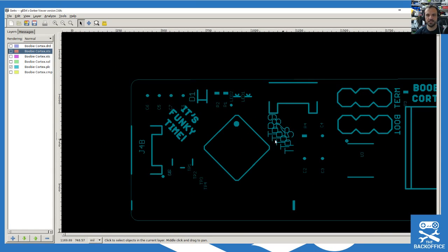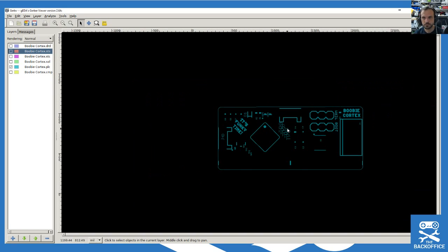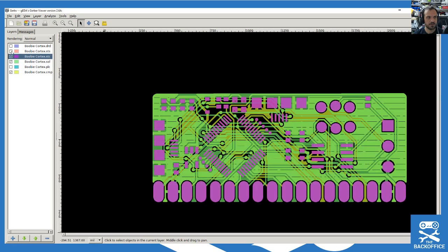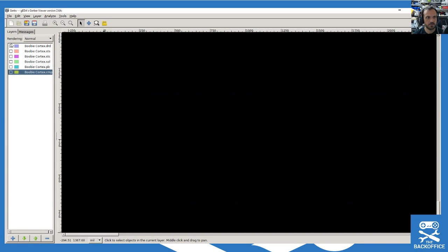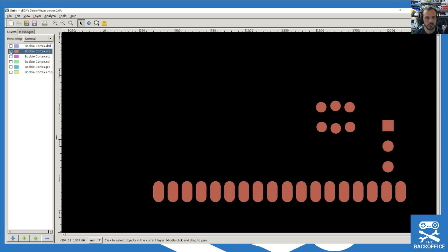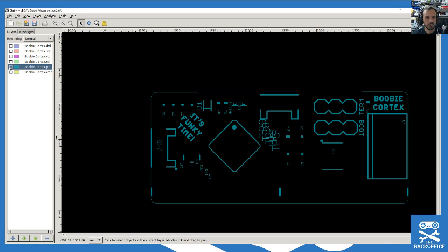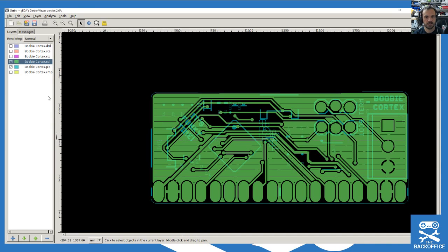So we want to turn off, we don't need the labels for those test points. So I'm just going to get a pen and paper and write that. Remove TP labels. Well, we can just do it now, actually. That looks quite cool. Where's our booby board logo? So I think there's a layer we haven't done, which is the bottom solder mask. Let's try one at a time. Nothing on there. Yeah, we don't have our funky logo output either.